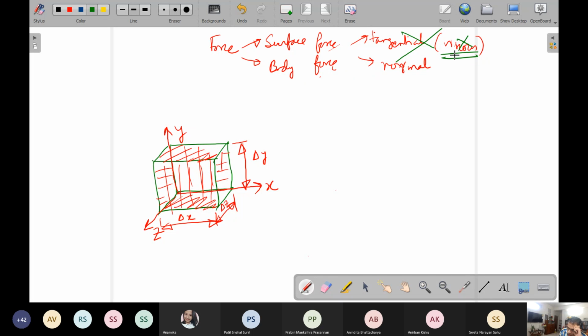The only consideration that comes into the picture is a normal force which could act even if viscous effects are not present. And when viscous effects are not present, the fluid is either static or undergoing uniform motion. Static fluid is one such limiting example. And when it's a static fluid, we all know from fluid statics that the normal force comes from the pressure of the fluid.